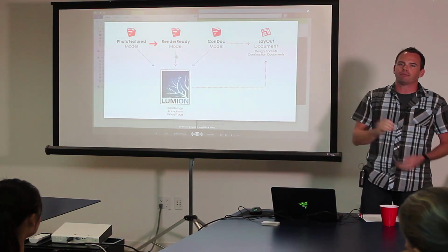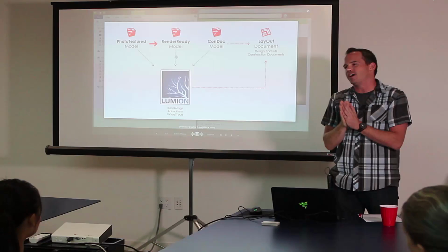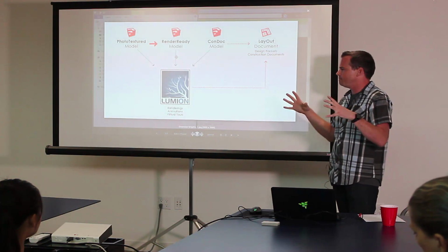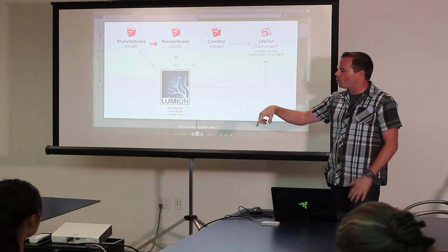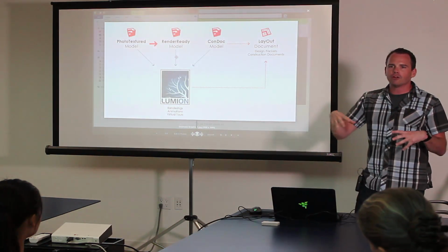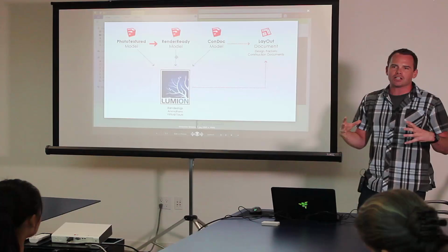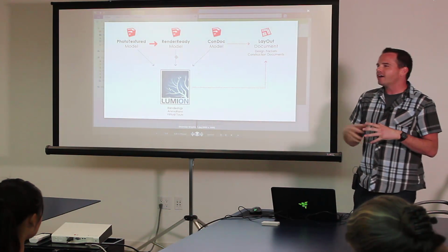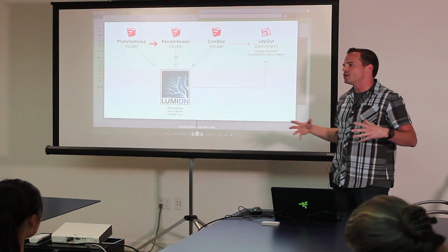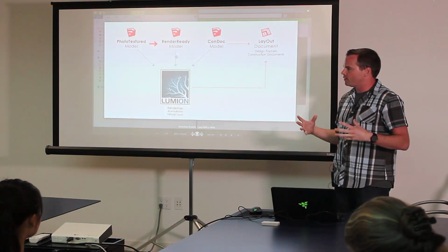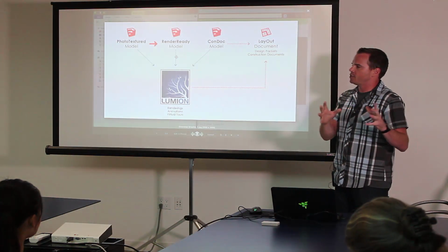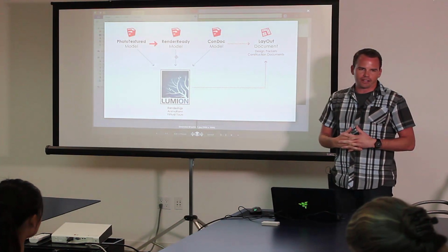A photo textured model is a loose, quick and dirty model. You take a picture of a building and you import the Google Earth imagery, and you're able to generate a 3D mass off of that photograph and that aerial imagery. So it's not super accurate. You don't go out there and measure the building, but you're able to generate this mass, and it's really excellent for context buildings in a visualization or shadow studies and things like that.